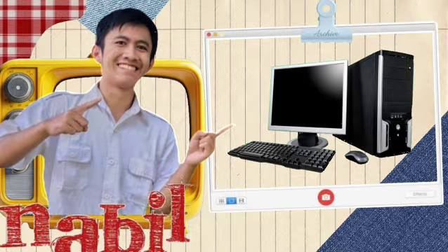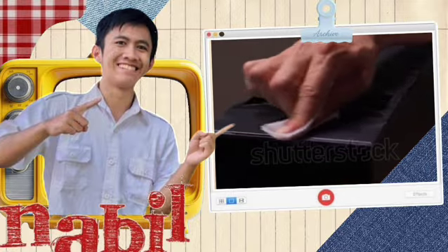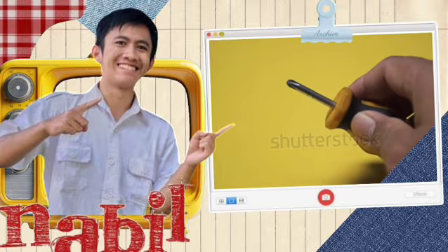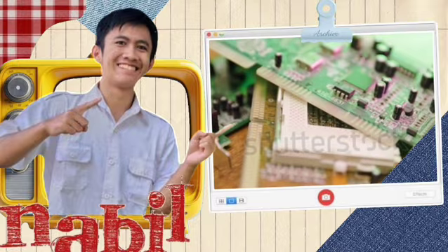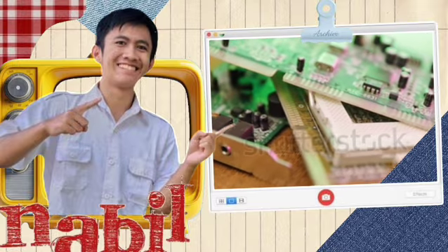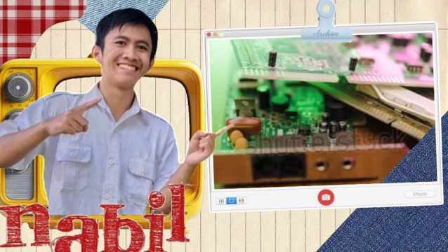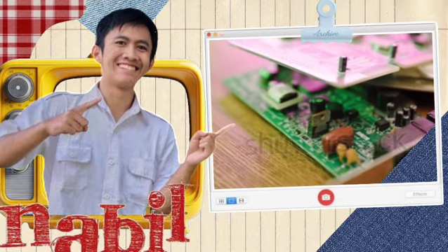Okay, now we are moving into how to assemble all the component parts and build a PC. Step 1. Before you begin, make sure you have a clean, well-lit workspace. You will need a Phillips screwdriver, some cable ties, and ideally an anti-static wrist strap to avoid damaging your components with static electricity. Lay down your case, motherboard, and all parts neatly on the table. Make sure you have grounded yourself. Just touch a metal surface or the PSU metal body to discharge static.